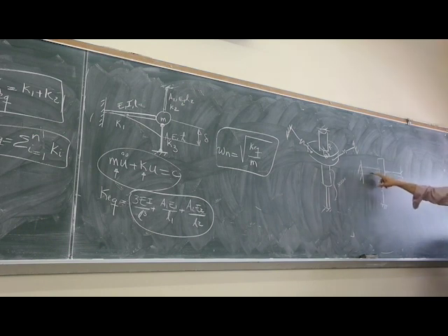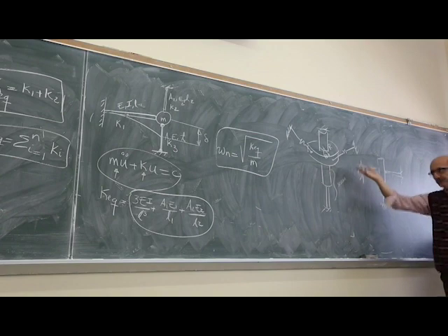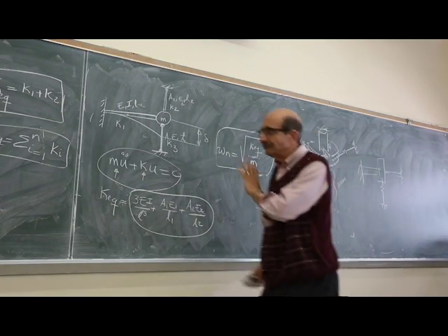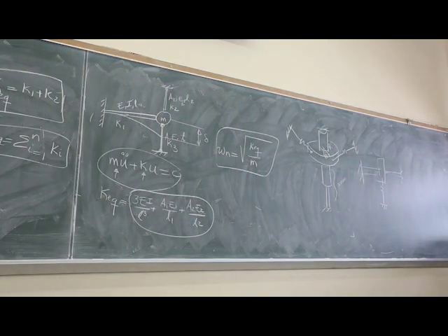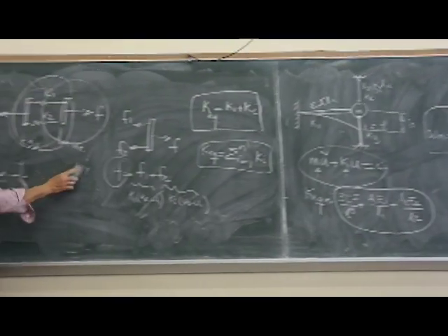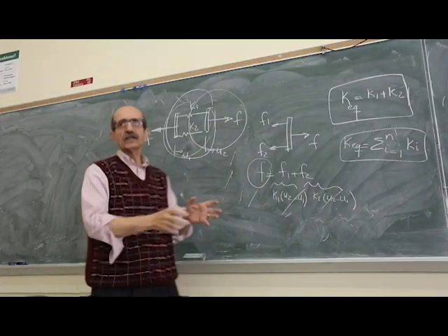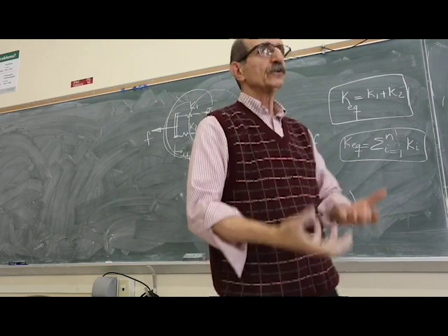This one and this one would experience the same deformation. So it would be all in parallel. So that's a good example. You may want to meet as a team and think about it, but it's not important to be able to apply these equations. The most important part is to figure out if those stiffness elements experience the same force or the same displacement.